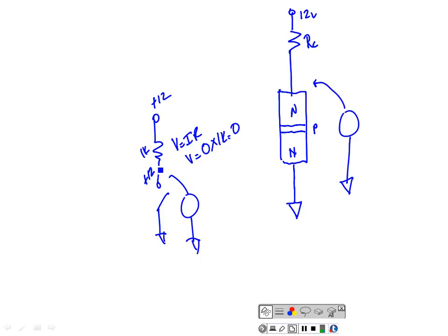So what voltage should you measure across a closed switch? 0 volts. A closed switch is supposed to have no resistance, right? So V is equal to I times R. I've got V equal to 15 amps times 0 ohms. How many volts do I have dropped across a closed switch? None. So you go across that switch and measure it with a voltmeter, you're going to measure 0 volts, and you're going to say, well, there's no voltage there. Right? You understand?